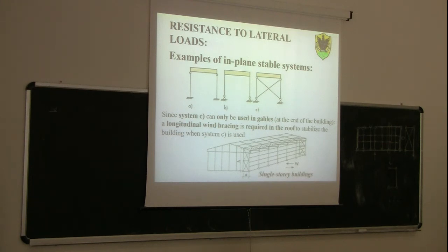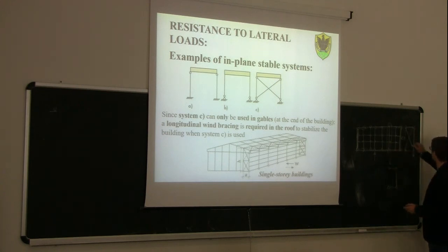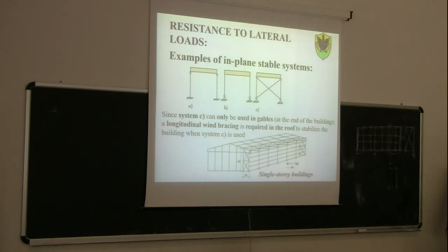Yes? Are we all sure about this? So how can I transfer this horizontal force here to this? You don't have basic systems. For the time being, the only basic system is here and here. Only here and here. The ones in between are done in this way. So if I push here, how can I make sure that this force will be transferred here and here? With purlins. With purlins. Yes, but are we able to do so if the purlins are ill-connected with the frame?